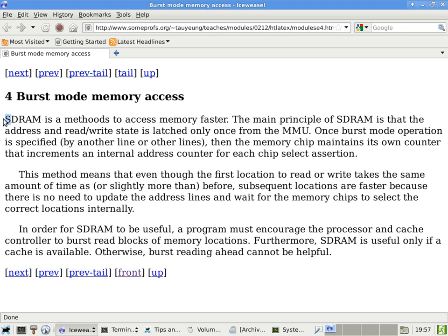Between the rising edge and the falling edge, it will also assume that in between two edges, I can also sample the data lines because it also represents the content of another location. So that's why we get the speed of transfer to be much faster than the actual clock speed of memory. When you go into the BIOS, you can actually see the clock speed of your memory bus. It is typically much slower than, say, 1600 megahertz.